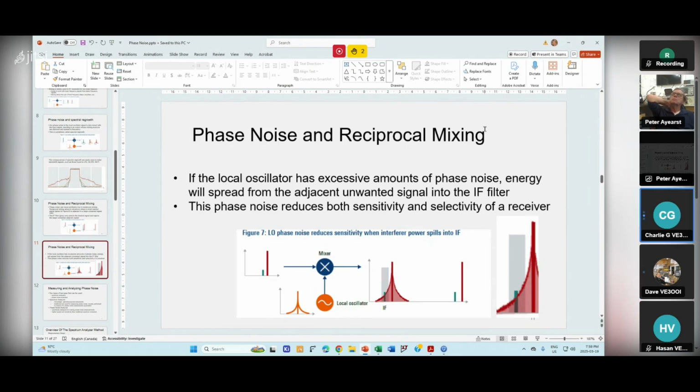Well, that goes into your budget, right? One of the specs in that will be the signal to noise ratio. So then you decide how much of that noise can be phase noise, and how much is coming from thermal noise of components and so on. You have to do the whole analysis, or put a wet finger in the air and make it as good as you can and live with it, right?